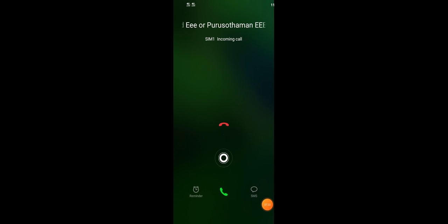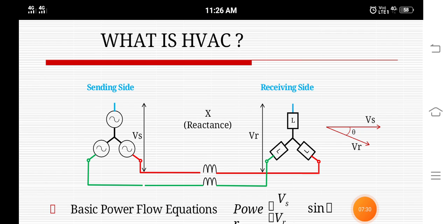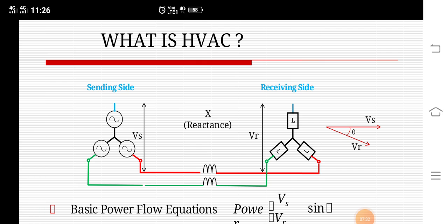Voltage control means the control of voltage in AC lines is complicated by the line charging and inductive voltage drops. The voltage profile in an AC line is relatively flat only for the fixed level of power transfer corresponding to surge impedance loading. Then the voltage profile varies with the line loading.